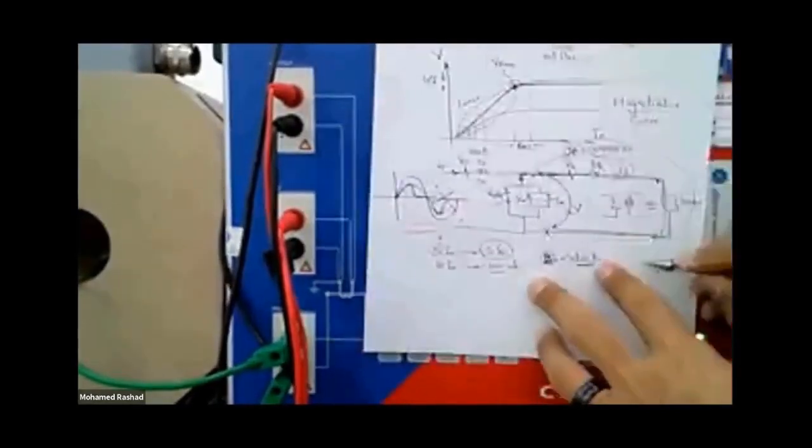So he told you, I will do something very simple. For me, as a device, I will not inject anything into the primary. I will leave it open. All right, and as for the terminals of this, I will come to you. You have connected me as a device now, and there is no load. Do I have any protection or metering device connected now? No. So as a CT analyzer device present here, I will connect two terminals here like this on these two terminals and inject voltage here.